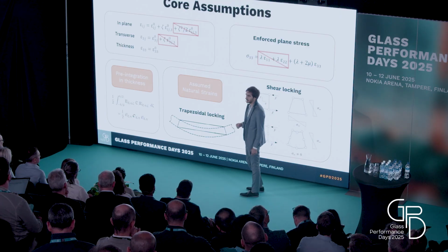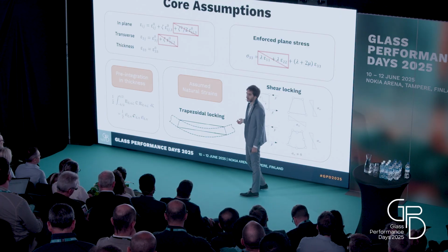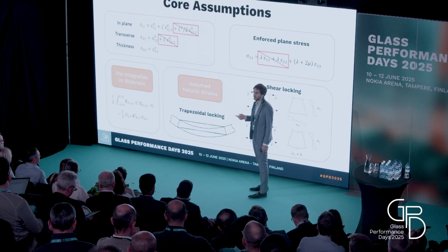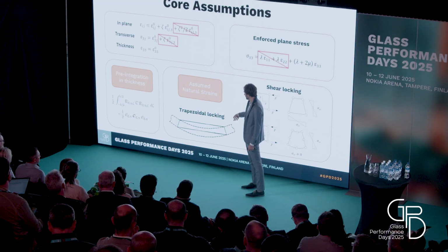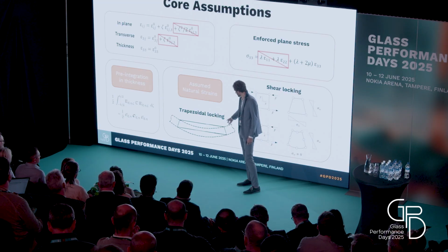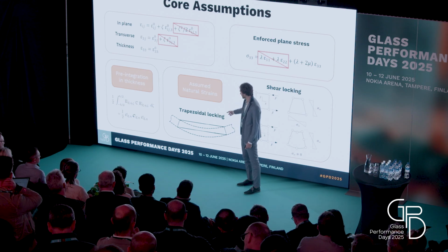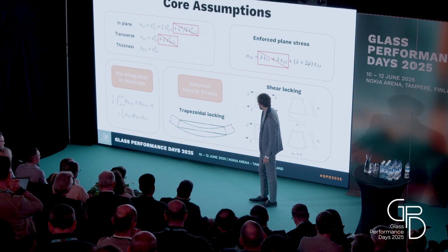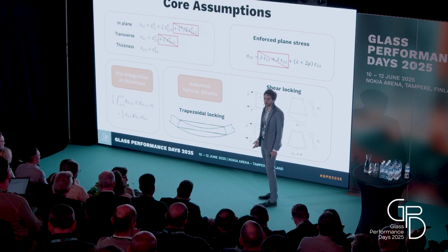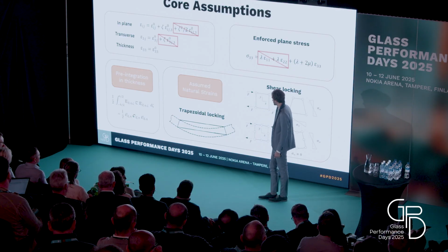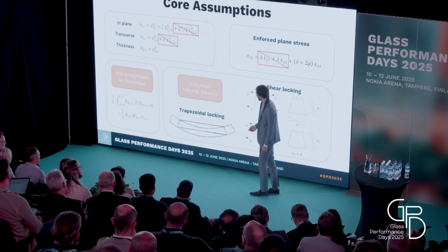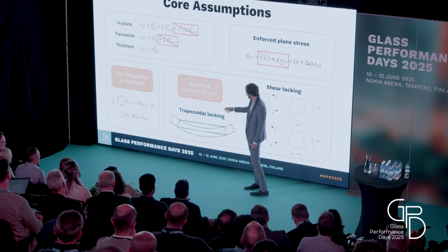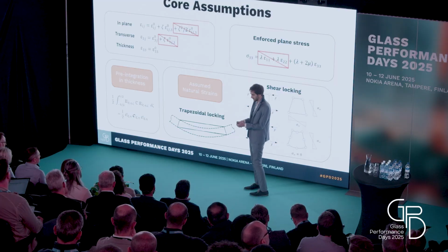The problem is that with a bilinear element, the thickness is correctly modeled only at the borders, and in the middle it's wrong because it's shorter, and this causes an artificial thickness strain. So, by assuming natural strains, you interpolate the thickness strain from the borders to the inside.